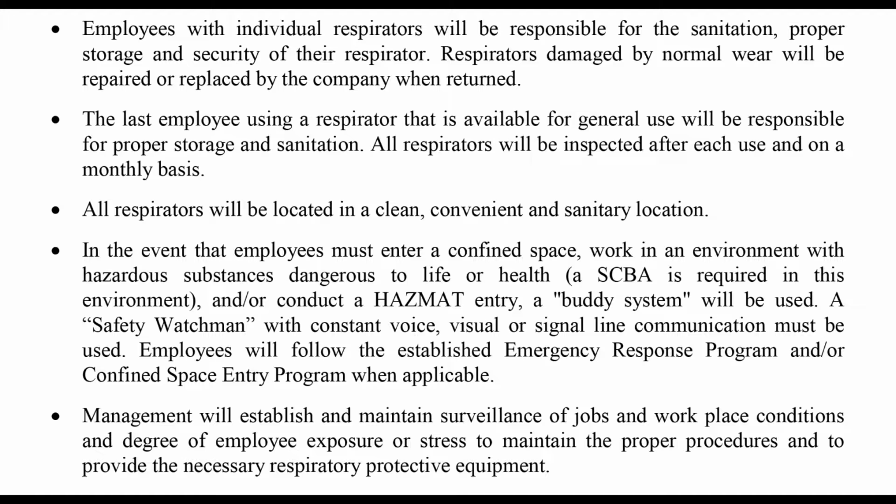In the event that employees must enter a confined space, work in an environment with hazardous substances dangerous to life or health where an SCBA is required, or conduct a hazmat entry, a buddy system will be used. A safety watchman with constant voice, visual, or signal line communication must be used. Employees will follow the established emergency response program and or confined space entry program when applicable.